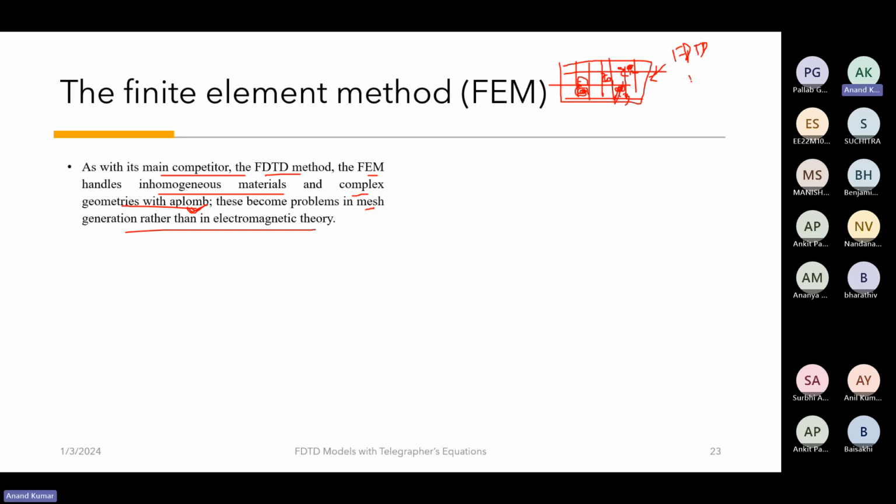And similarly in FEM as well, if you are using this sheet, you can discretize using these triangles or tetrahedral structures, and if you just assign these epsilon values correctly while meshing, then you are all right and you don't have to worry about it, because the formulation dictates that these will be solved as one structure whose dependence is calculated within.